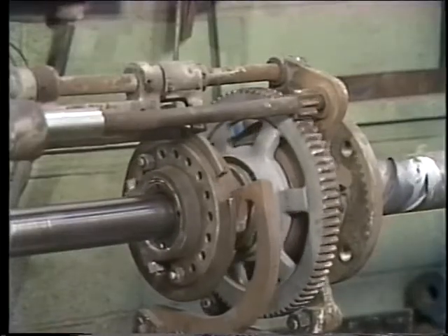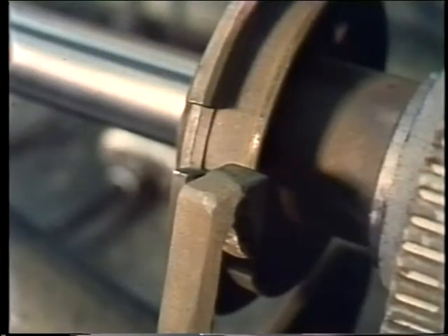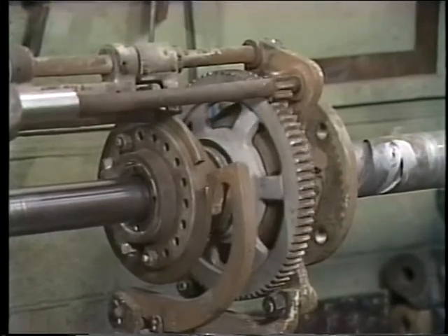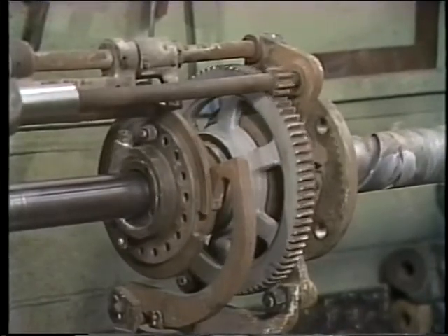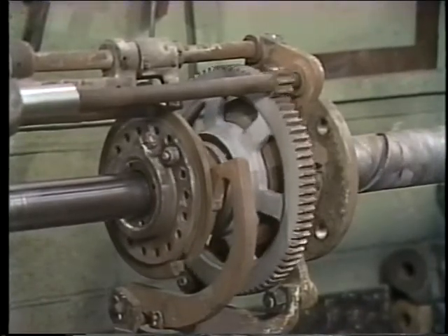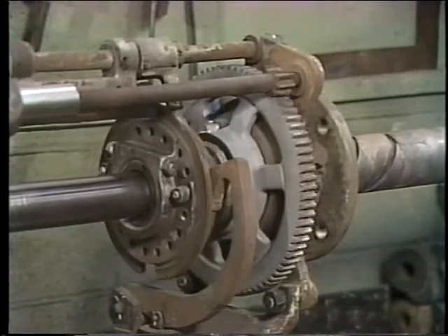The way the cam actuates the valve is basically the same on a stationary rotating soot blower. Only on a stationary rotating soot blower, there's no need to drive the element out and back in. The cam of a rotating or a short retractable soot blower determines how long the blowing medium blows while the element is rotating.